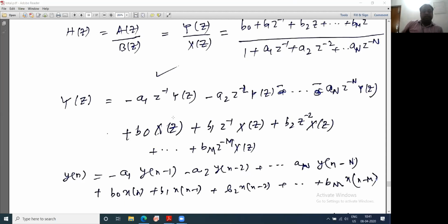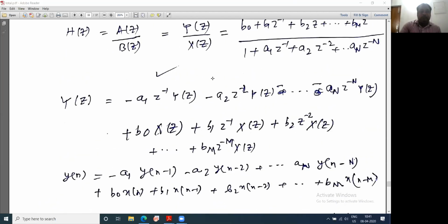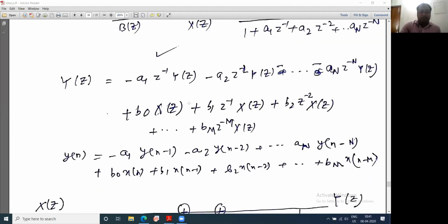Yesterday we discussed direct form 1 realization, right? Direct form 1 realization, then I said I can write Y(z) equal to this. If you cross multiply, then Y(z) will be multiplied by this denominator, X(z) will be multiplied by the numerator. Then you take everything to the right hand side, keeping Y(z) on the left hand side, and you get this expression. If you take the inverse, Y(z) becomes y(n), and correspondingly the inverse of every term is mentioned here.